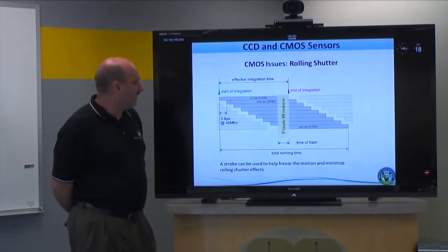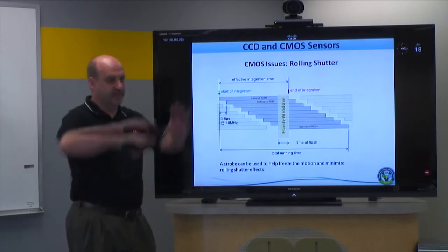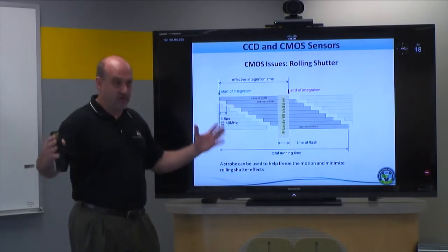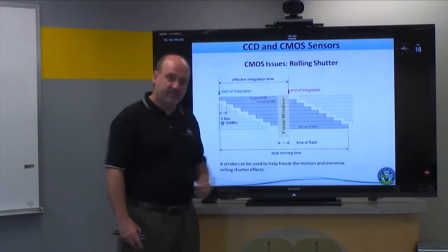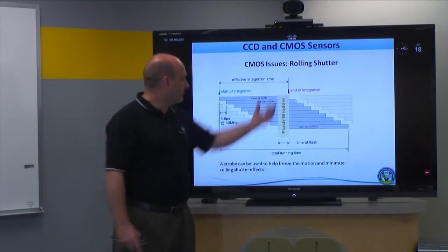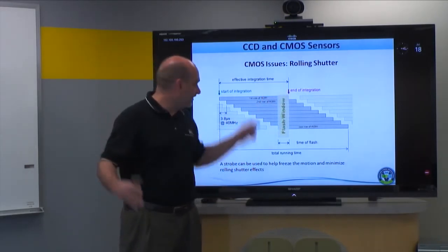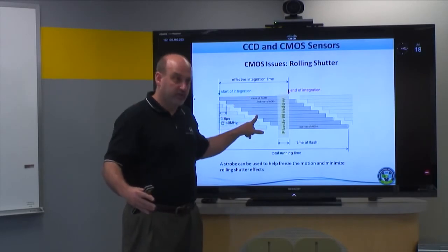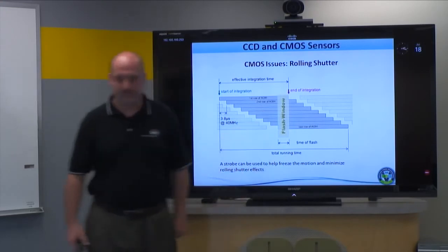The only caveat is that in a machine vision application, if you can have an entirely black background where there's no external light leakage, and you can set off a strobe, then there's a chance to freeze the motion in a rolling shutter type of scenario with a strobe. But again, you have to have a very controlled circumstance and let no light hit in other parts of the area where the line is photosensitive, but you do not want to see the integration of that light.